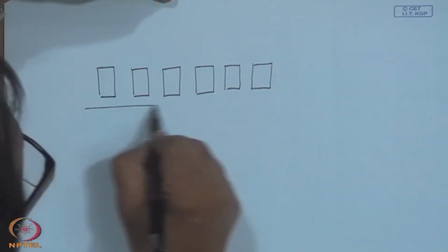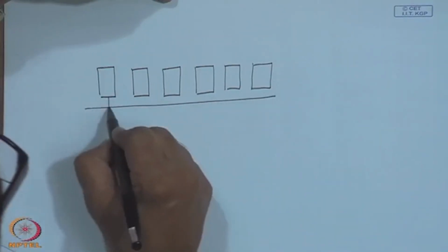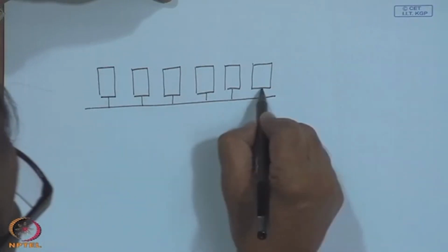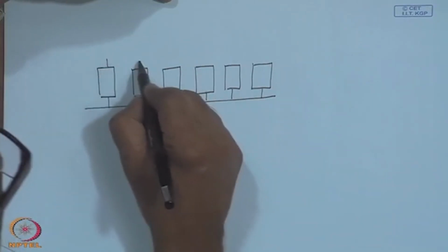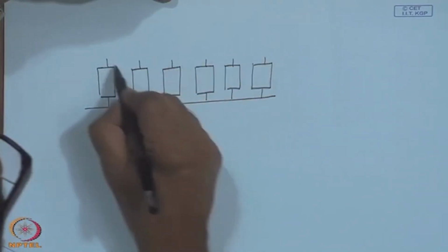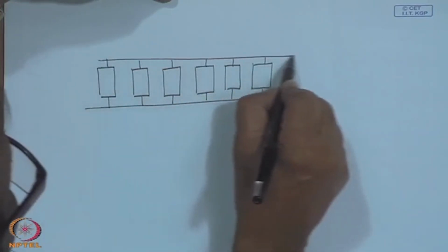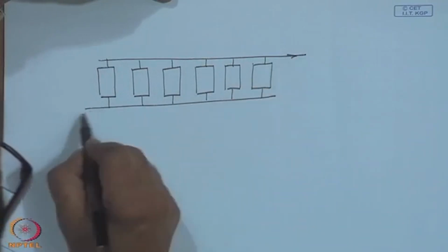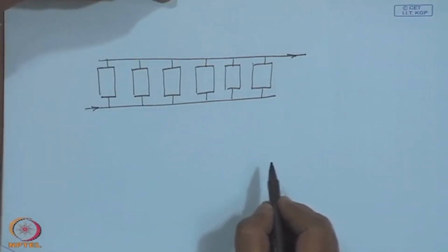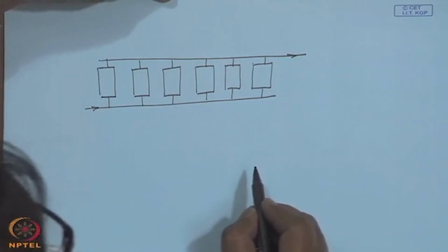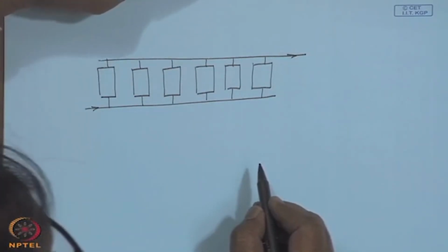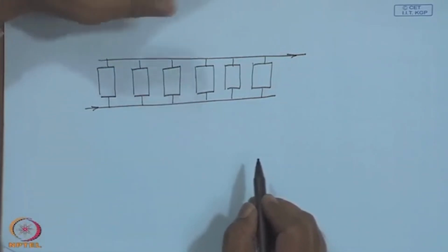So, let us say there is a large header connected to this, connected to this, connected to this, and all the 6. Then again the delivered hot water will come out through these 6 collectors, and I have some sort of a pressure balancing, so that the flow through each collector is uniform, in addition to the headers and risers that we discussed providing uniform flow in the collector. This is one arrangement.